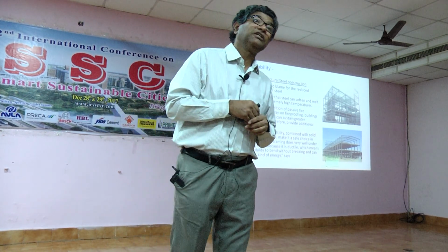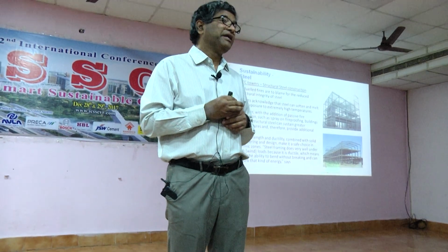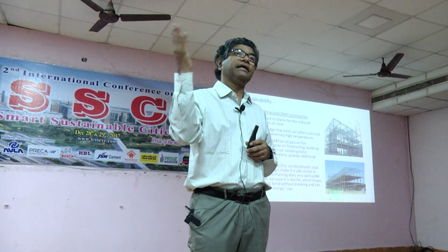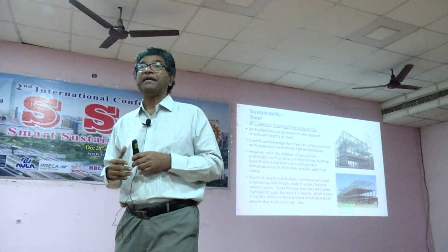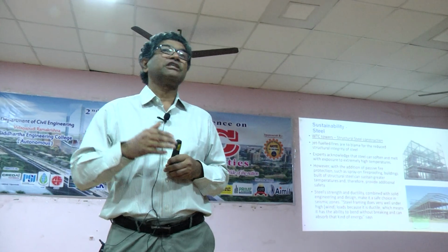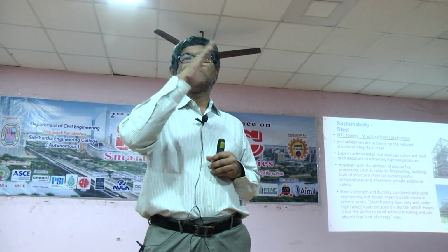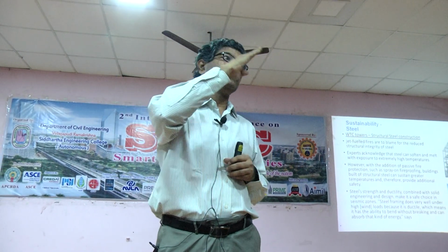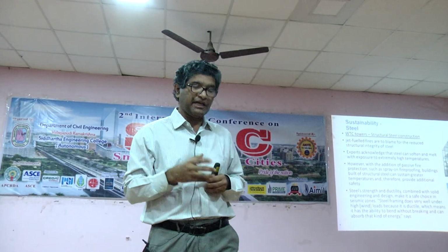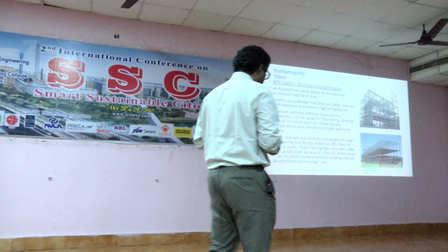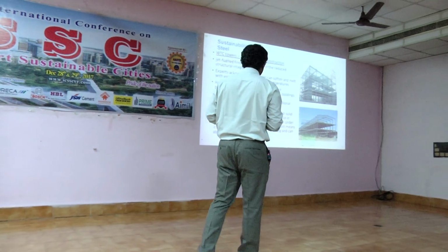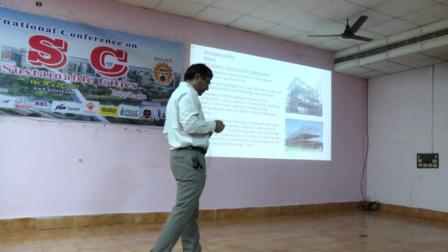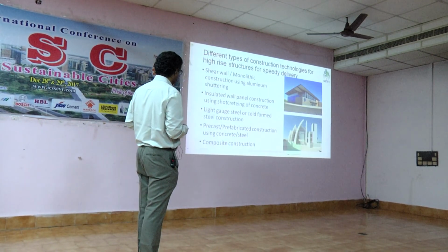And because steel is so ductile, they made sure that the steel can take the fatigue that is going to develop as the structure deviates on the top by 1 meter daily, this side and that side, right? So steel being ductile, it can take that much movement and the fatigue that is going to result from that movement, right?